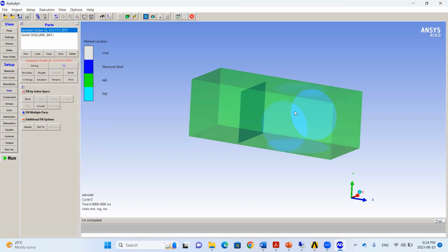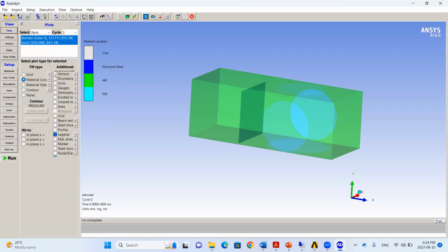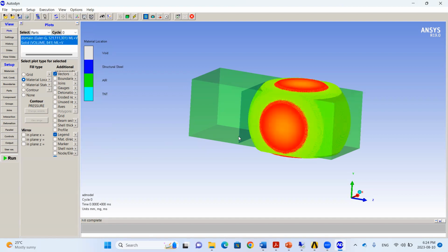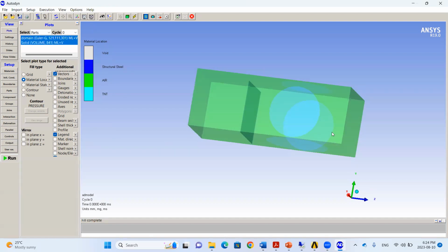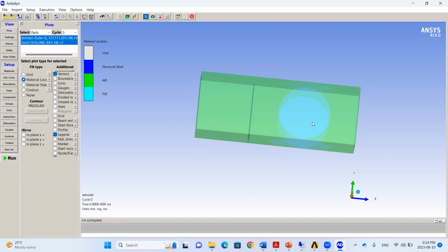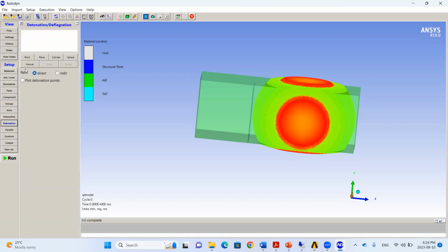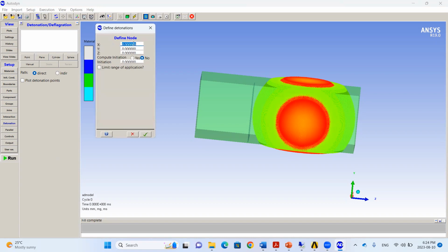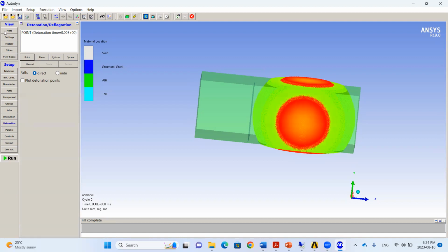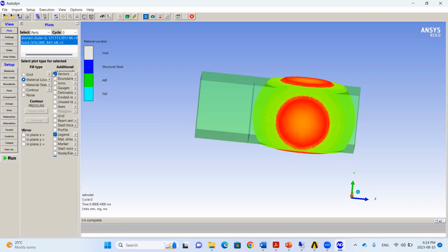So we found here our vectors. We can press the vectors to show, and this is our vectors. It is just before the steel plate. Don't forget to put our detonator as a point at the center of the vectors, which is 500, 500, 1000. Now we'll turn off the vectors.